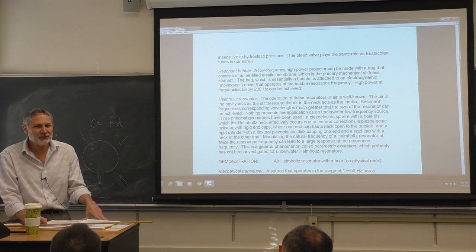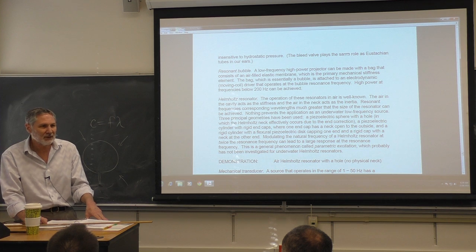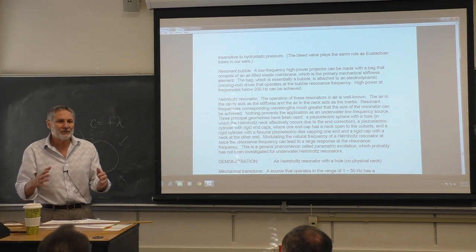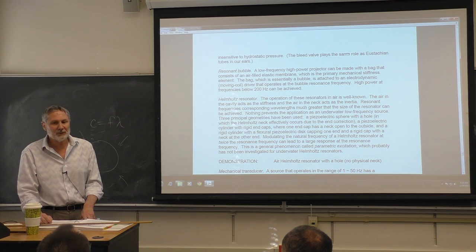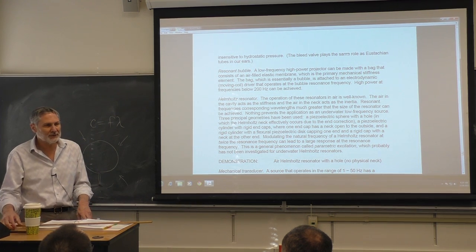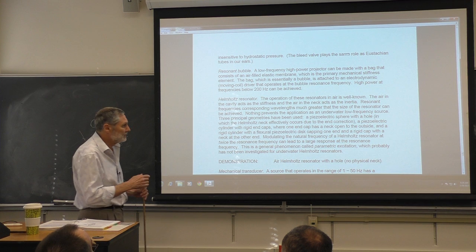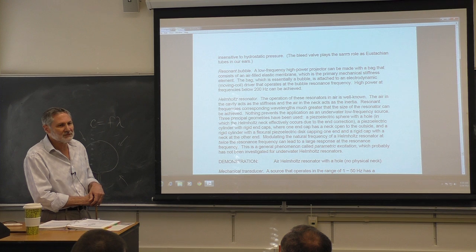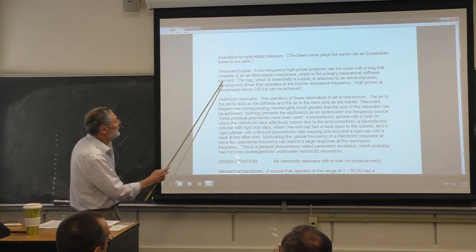They need huge forces, and it's low frequency. It's hydraulics. They're using hydraulics, pistons, cylinders. But on a smaller scale, shakers are loudspeakers. And we have a number of them. I have several myself. I've used them a lot in research and demonstrations. They're essentially a moving coil, just like a loudspeaker. So you can use that to drive this.